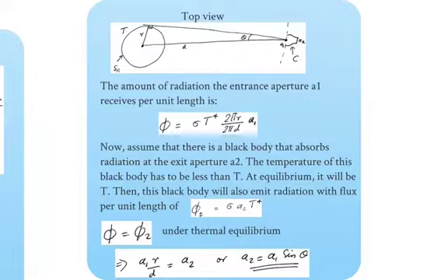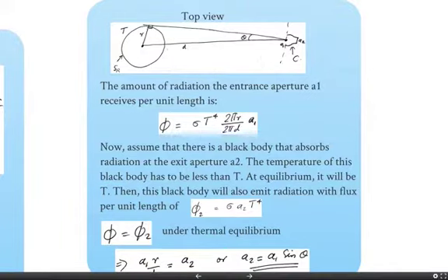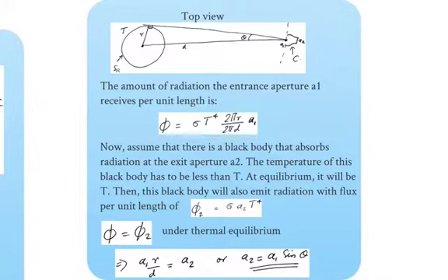Another way to draw a conclusion from this equation is that here we did not make any assumptions about what the geometry of the CPC is. We did not say it was a parabola, right? But we ended up with the same equation. So another way to say this same thing is that now we can conclude that the best you can do from thermodynamics is this, which is the same as what a CPC does, which means that the CPC is the best you can do based on thermodynamics. Okay, so it's kind of a logical argument.